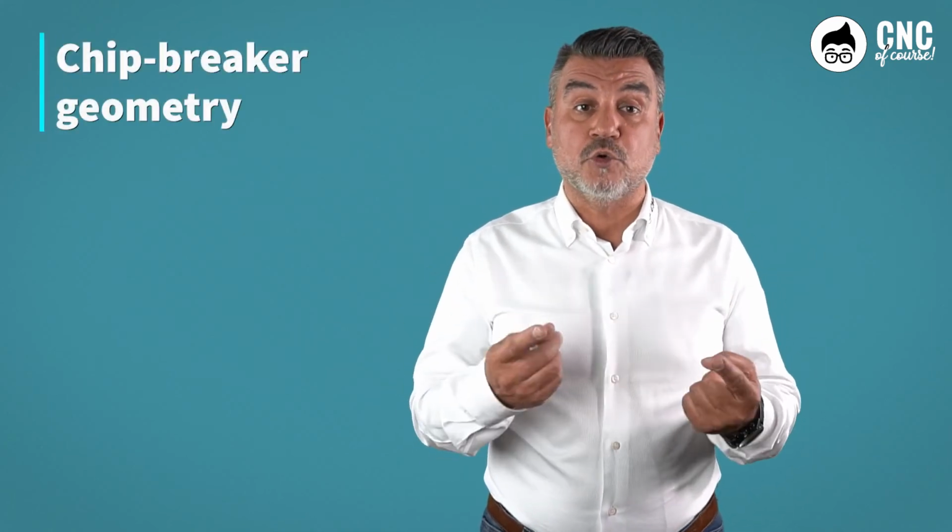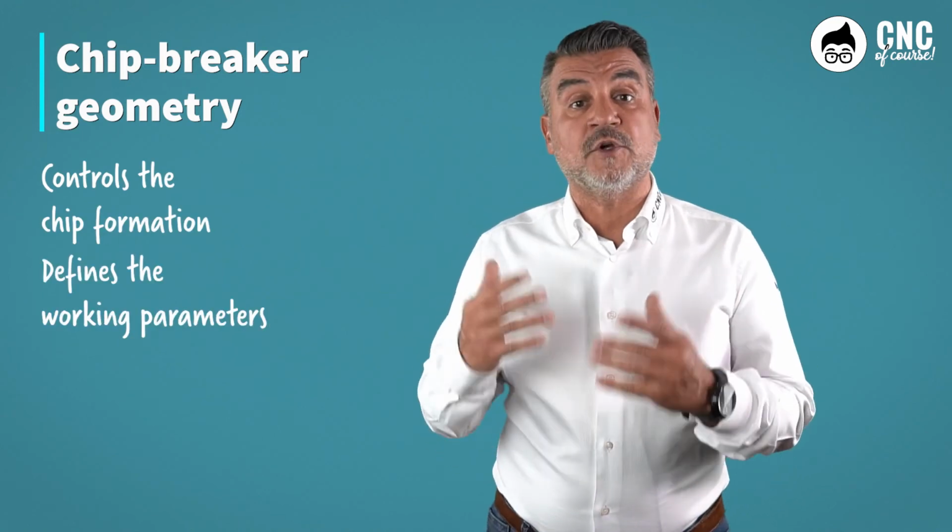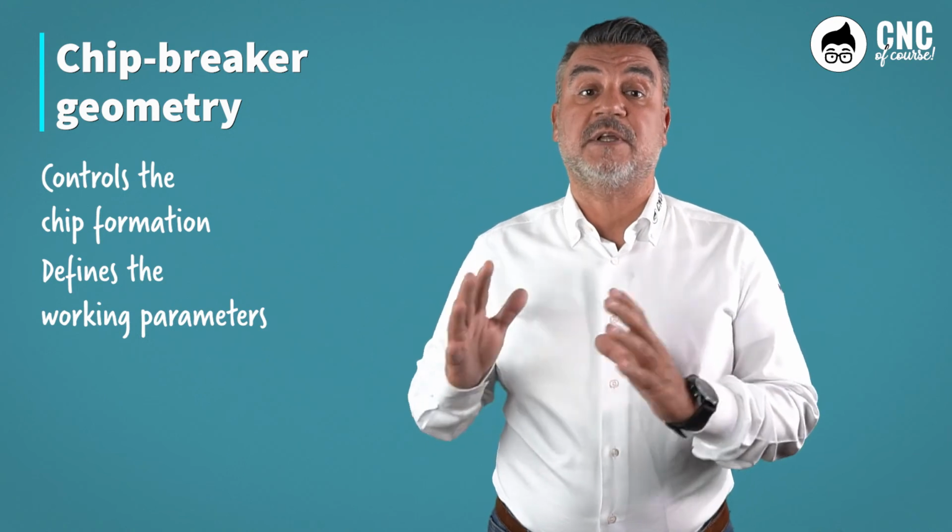Not at all. They are the result of very in-depth research, and are created to be able to control the chip in very precise fields of application, roughing and side finishing, and will depend on the material that the insert will be machining. Basically, the inserts Research and Development Center, after analyzing the machinability of a family of materials, designs the chip breaker geometry to allow machining with correct control of chip formation, and defines the working parameters, depth of cut, and feed rate for which this geometry was designed.